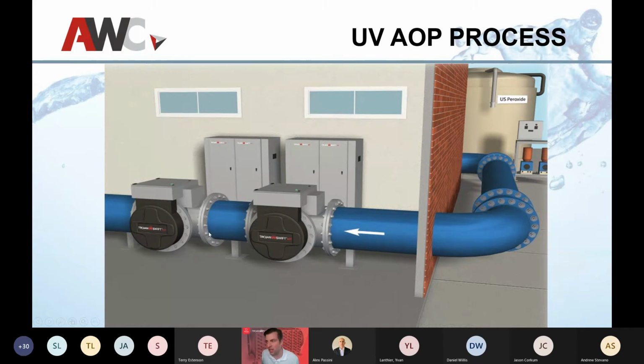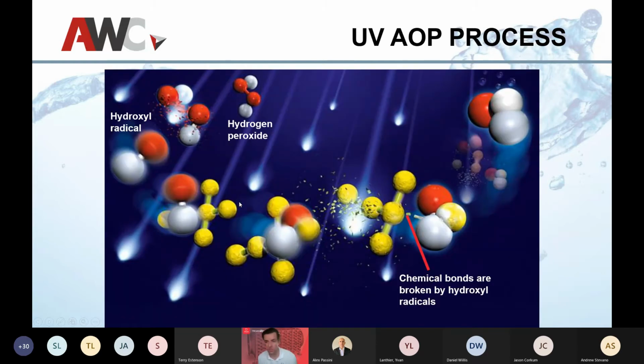Usually an oxidant is stored in a container, and you also have a dosing skid, some oxidant water, and a series of UV chambers, the bigger part of this particular image. Inside these UV chambers is where the so-called magic happens of chemical contaminants. This happens through two sorts of processes that are happening instantaneously inside a UV chamber. First, you have direct UV photolysis, in which UV light interacts directly with a particular contaminant. That contaminant absorbs UV, and that results in the breakdown of its molecular structure.